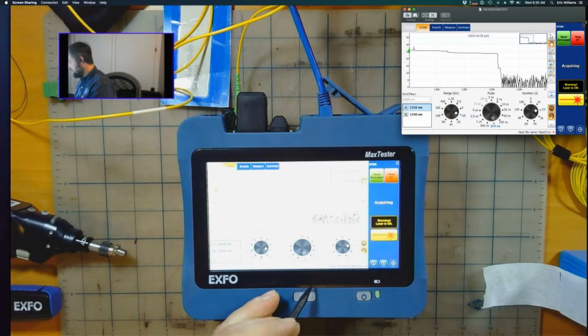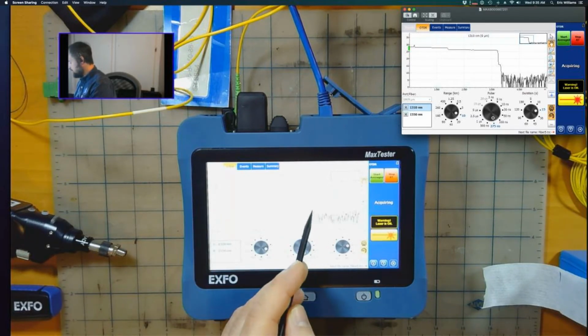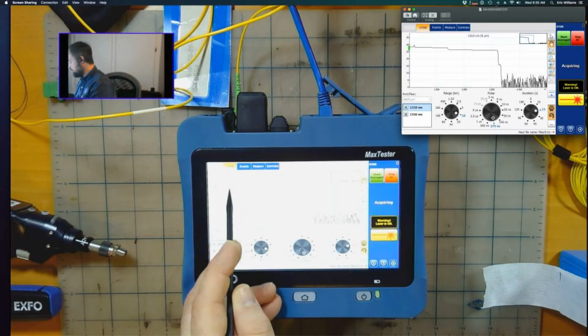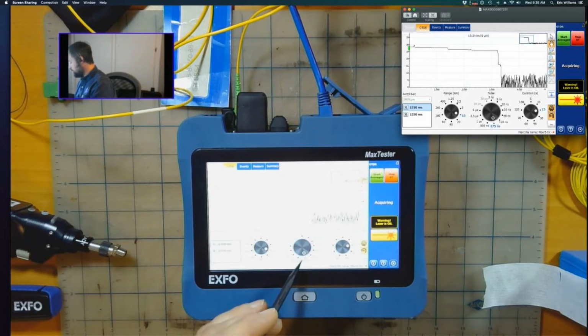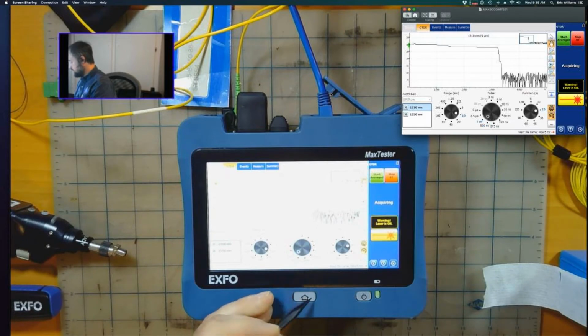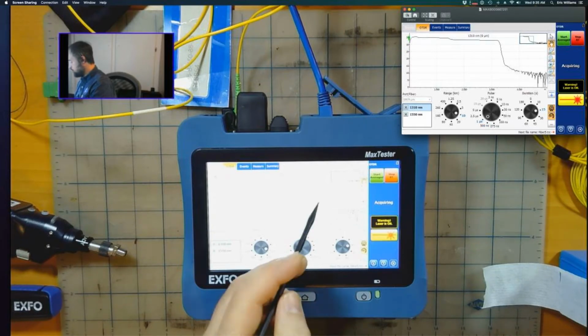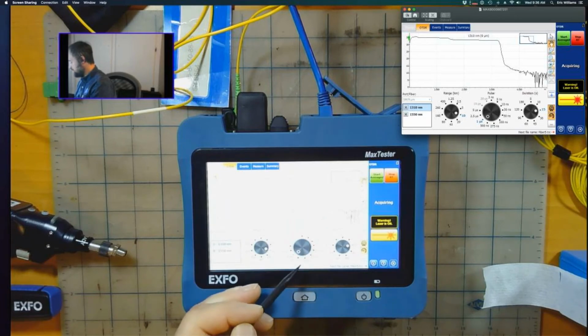So it can get a little bit confusing with the OTDR if you're not used to evaluating traces with splitters. You're going to see this and think, man, that's really unusual. Here's a big loss of about 10 dB, and then really only 100 meters to another large loss with a lot of reflection. And even with a larger pulse width, I'm still going to struggle to get my trace all the way out past there.